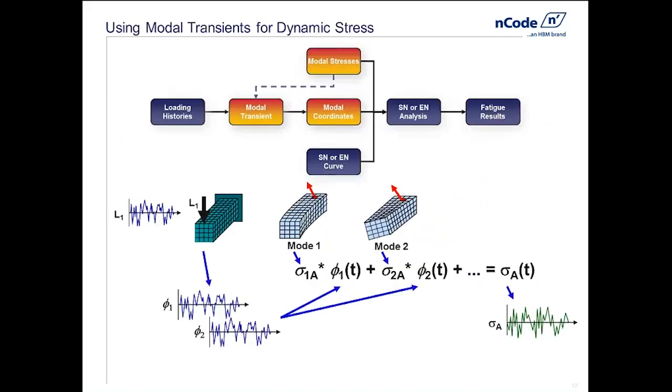One of the challenges was how do we deal with complicated dynamics of a very large structure? For example, in a vehicle white body, we might have 200 or more modes of vibration that we need to account for. We need to account for the dynamic stresses that arise from all of these modes. Now, if you didn't know any better, you might say, let's do everything as a direct transient analysis in FEA. The problem is that's computationally impossible, or very, very difficult, especially when working with a large number of time steps as we've been talking about in this type of arena.